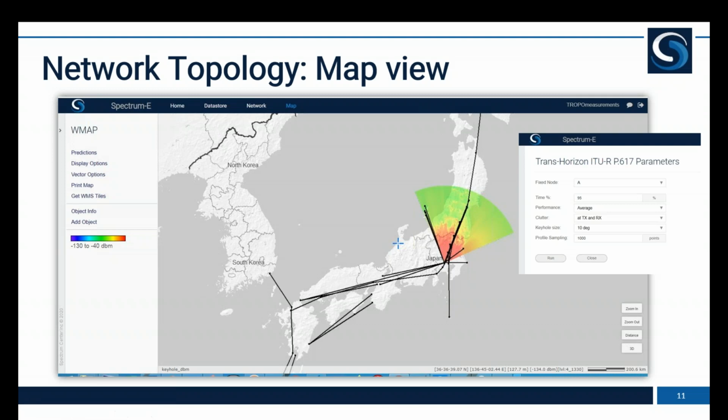Why? Because when you're deploying the systems, your intended receivers, you want to know where to put those receivers, right? The software helps you to determine how many kilometers, let's say to the left, to the right, or back, that you can actually move your receiver to in order to receive a better signal. So if you have a color on this propagation plot that is higher in field strength, you can actually pick up the receiver and move it to where you have a better signal reception and hence improve your signal.